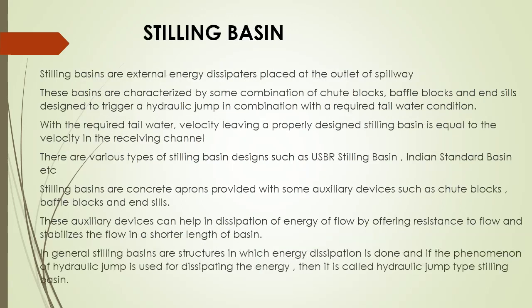Next we are discussing stilling basins. Stilling basins are external energy dissipators placed at the outlet of spillway. These basins are characterized by some combination of chute blocks, baffle blocks and end sills, designed to trigger a hydraulic jump in combination with a required tailwater condition. With the required tailwater, velocity leaving a properly designed stilling basin is equal to the velocity in the receiving channel. There are various types of stilling basin designs, such as USBR stilling basin, Indian Standard Basin, etc.